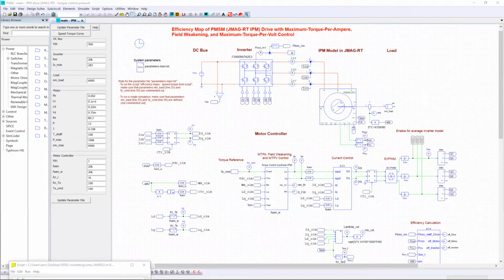As you may know, the efficiency map of a motor drive system is an important output, as it gives system engineers a nice picture of the overall efficiency of the drive and what operating point to operate at for maximum efficiency. The generation of the efficiency map of a PMSM drive system could also ask some extra effort and time, because it involves comprehensive load testing of the complete PMSM drive system with a motor dynamometer. The workload, time, and cost prohibit such activity most of the time.